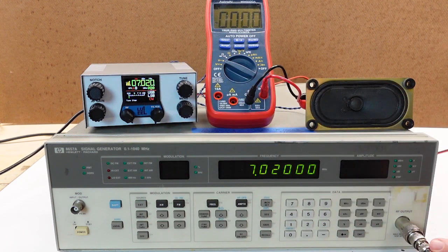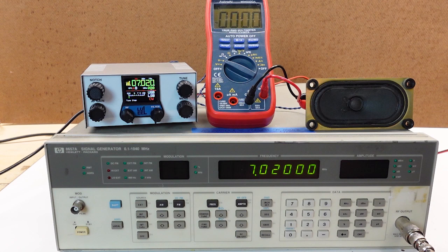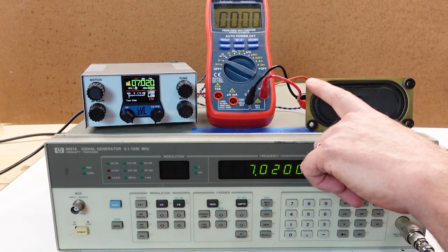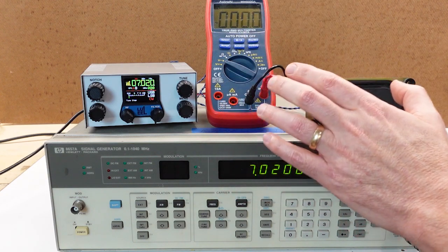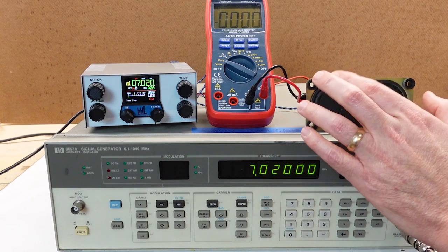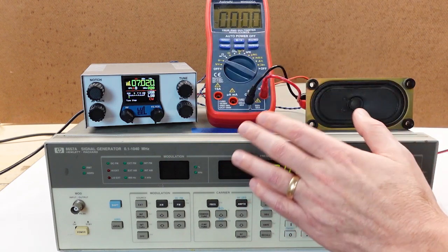That's mainly just to provide a good impedance match from the output of the signal generator. The input of the receiver may or may not be a good solid 50 ohms, and I know this 20 dB attenuator is, so I just have to factor that in when I do the actual calculations. No big deal. I have the speaker connected, and across the speaker I have the only thing I can really use to check for the difference in the voltage output to determine the minimum signal. I just put it in AC mode.